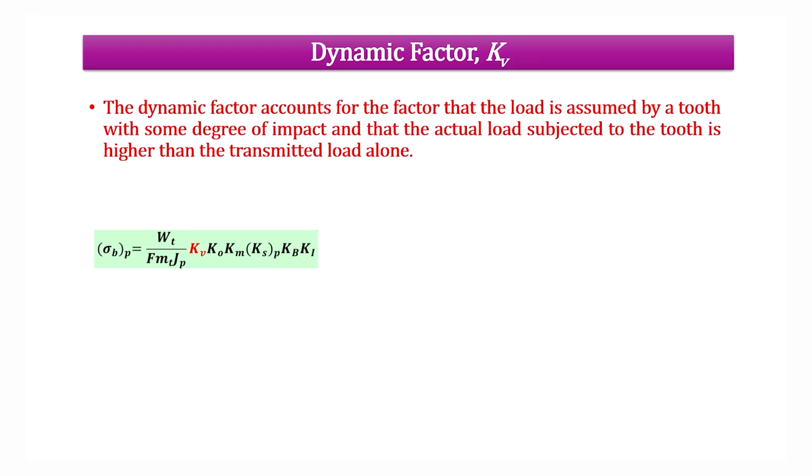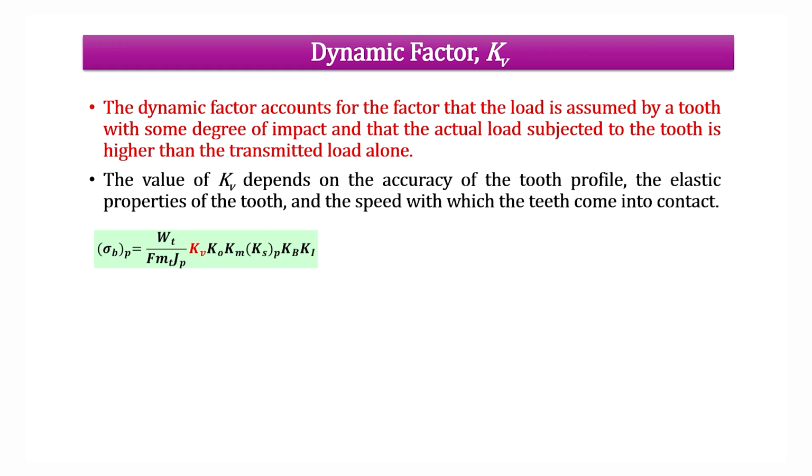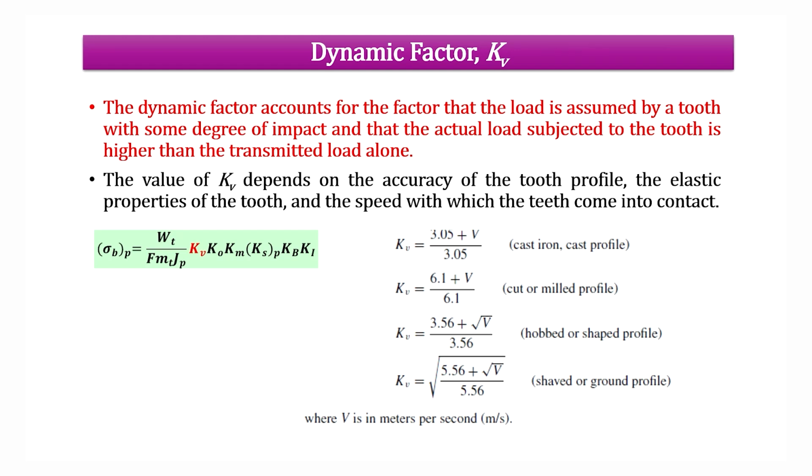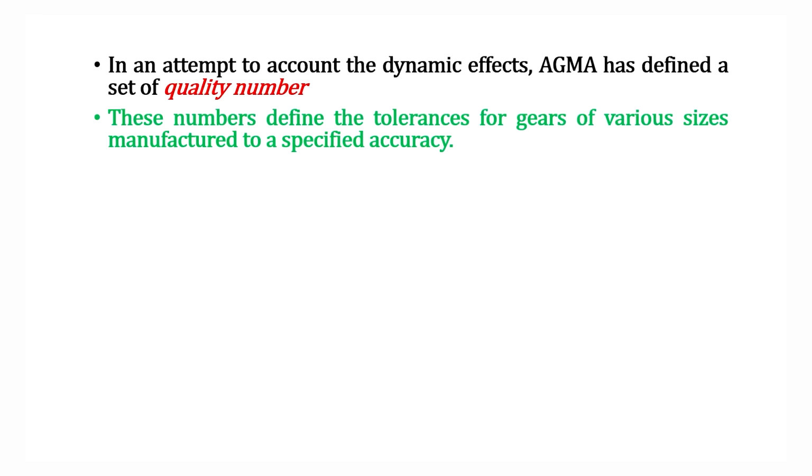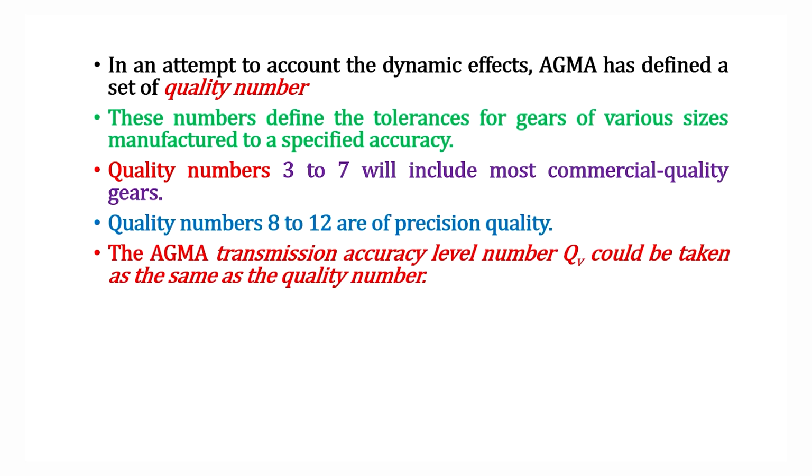Now, the dynamic factor. The original equation of bending stress was derived considering the static case, but it is not the case of static. The gears are moving or rotating and there will be a dynamic effect. And so, the dynamic effect is obtained either from this Barth equation or from the AGMA equation knowing the quality number.